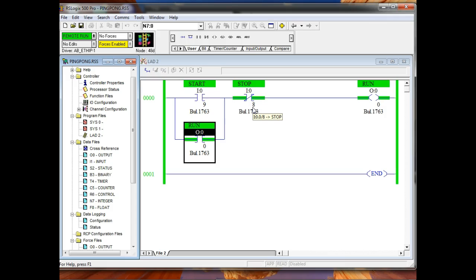We would use a normally closed push button. And this is what gets students coming out of motor controls. This is what gives them problems, because they take a motor control diagram and they convert it over to PLC data, and they're using a normally closed push button, and they want to give it a what? A normally closed symbol, right? You understand that? Now this is the problem right here.